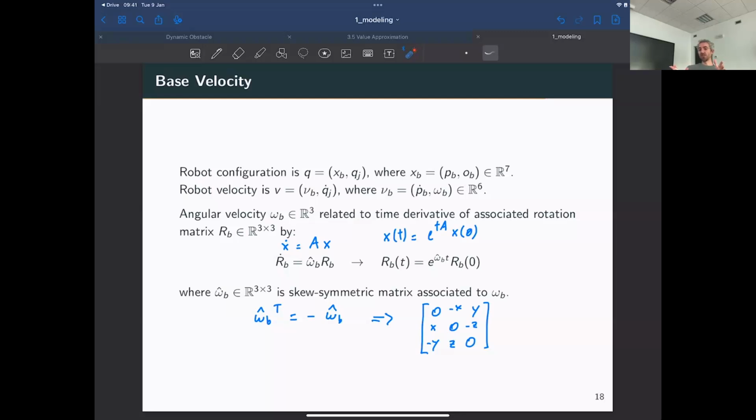In the end, if I need to visualize a rotation, I need either a 3D viewer that shows me that rigid body in that orientation so I can see it, or I need to convert the quaternion or rotation matrix into Euler angles and then do these 3 plots, because that's the only thing I can understand as a human being. And I share that feature with most human beings. I've never heard of anybody who plots the rotation matrix or the quaternion. So yeah, that's my very honest answer.